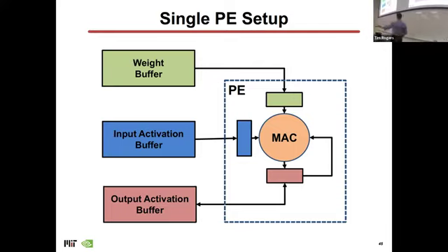Let's take a step back, and regardless of which pattern I'm using, let's assume that I've loaded things in. I've got registers on these things that store the things I need to do in the MAC. MAC is just multiply accumulate. So there's sort of an accumulator, right? If you've ever done ISA design, the accumulator ISA design takes the last product and puts it back into the execution unit. And then I take in these other two things that I'm multiplying, the weight and the activation, and that is the core of what the processing element does.